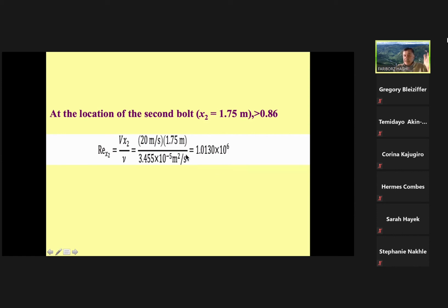When Reynolds number is more than 500,000, that shows it's turbulent. And then we look at the equation that we have for turbulent, the local heat transfer. Again, the local heat transfer that we have, and we place it there. It's a constant times Reynolds number 0.8, Prandtl number 1/3, okay? Again, please write those equations that you need. You can bring 2 pages of equations, 2 pages back and forth, which means a total of 4. And if it's a table, equations given in a table like 7.1, I will provide you, okay?